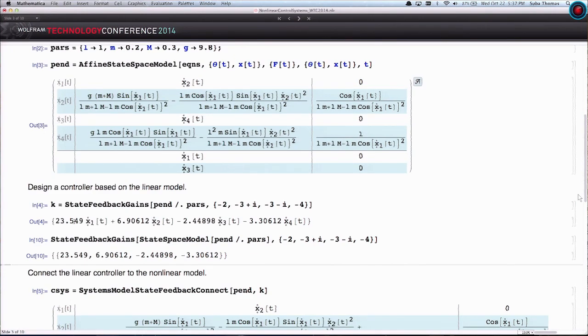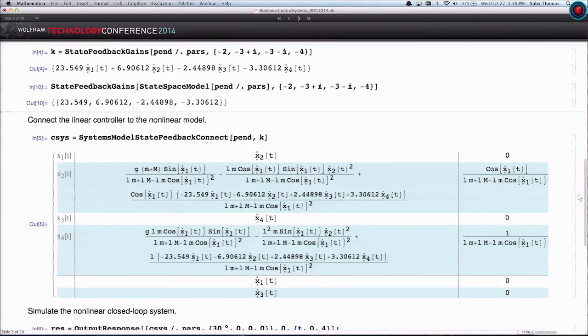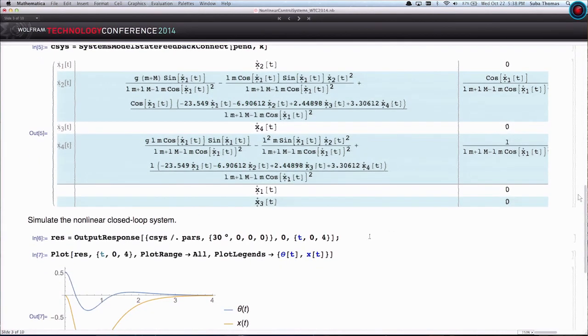This is actually the control law given as a list, because there's only one control input, there's only one element. And the reason it's like this is in case you have operating points that are non-zero, the gains will not completely capture all the information. But both these will automatically work with the next step, which is to connect the plant and the controller. So if we connect the plant and the controller together, this is the closed loop system of the unstable pendulum with that controller. And then we can simulate it.